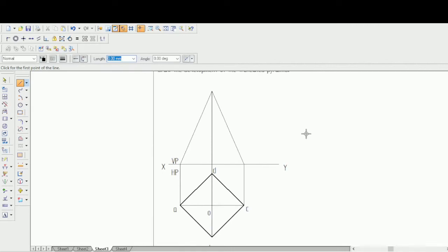So the next thing you'll have to do is draw the cutting plane. Use the cutting plane: you can go to this line command and select the cutting plane line type here, because if you select this one, it will be similar to a hidden line. So let's select something like this. Exactly at the axis, okay, you can just read the question clearly.